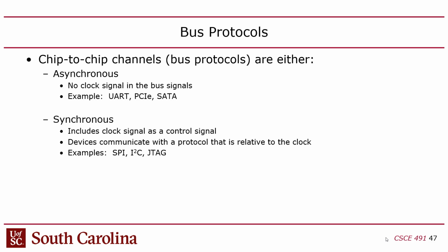So if you have a 10-bit, 8-bit encoding and you're sending just zeros, say you're just sending zeros, that 0 is actually encoded as 10 bits where it's not all zeros. There's actually transitions. And that allows the receiving side to use a circuit called a phase lock loop to extract the clock signal from the data. It can figure out what the clock is based on the data, assuming the data is going from 1 to 0 and 0 to 1 frequently enough. Does that make sense? So that's another way.